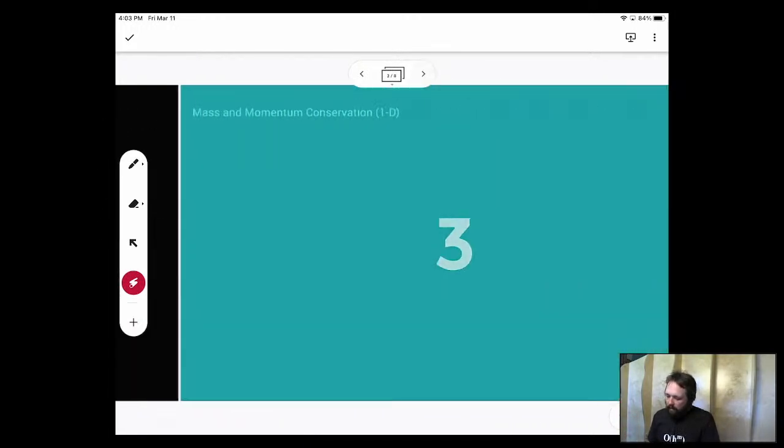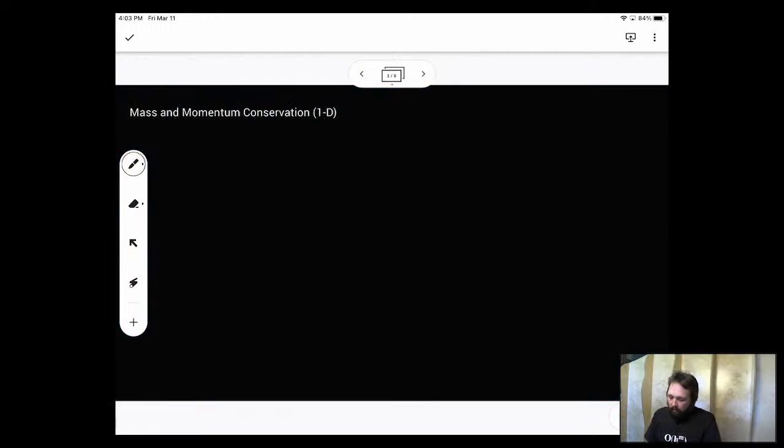But what we'll be working with today is in 1D. In the equations we're going to be starting with for the volume, we have the time derivative of the fluid height. This is the difference between the free surface height and the bottom topography, and it's just going to change due to volume flux divergences. And then the momentum equation. What we're going to be tracking is the velocity integrated over a fluid column. So we have advective fluxes that contribute to that, as well as pressure gradient forces. And on the right-hand side, we have a term that accounts for variable bottom topography.